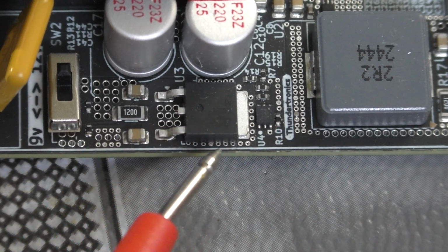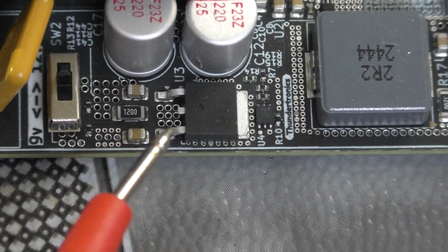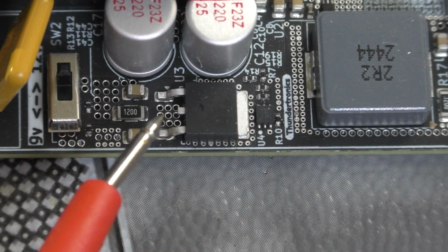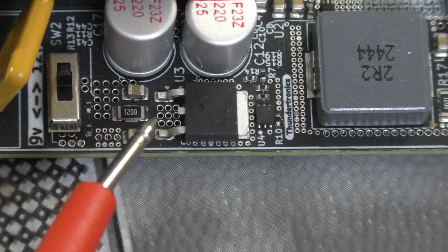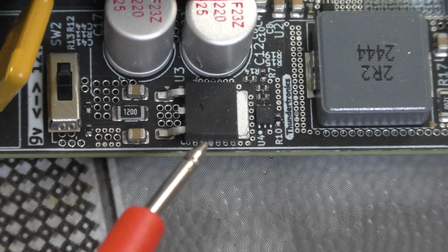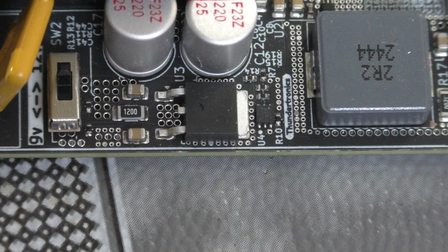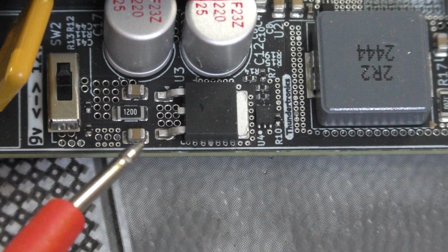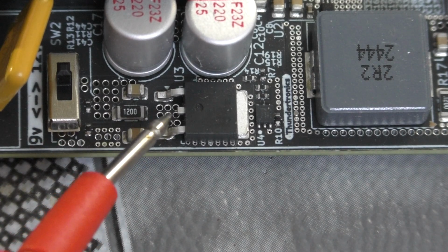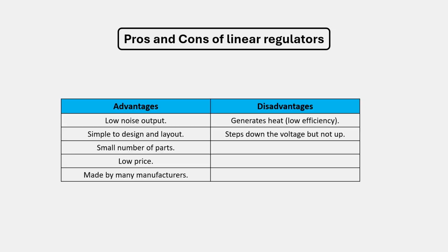And as you notice, I put a lot of thermal vias around this device from all directions, especially from here. These are the inputs of 15 volts, and all around here are basically another type of thermal vias connected to the output. So these are thermal vias for the input. These are thermal vias for the output.